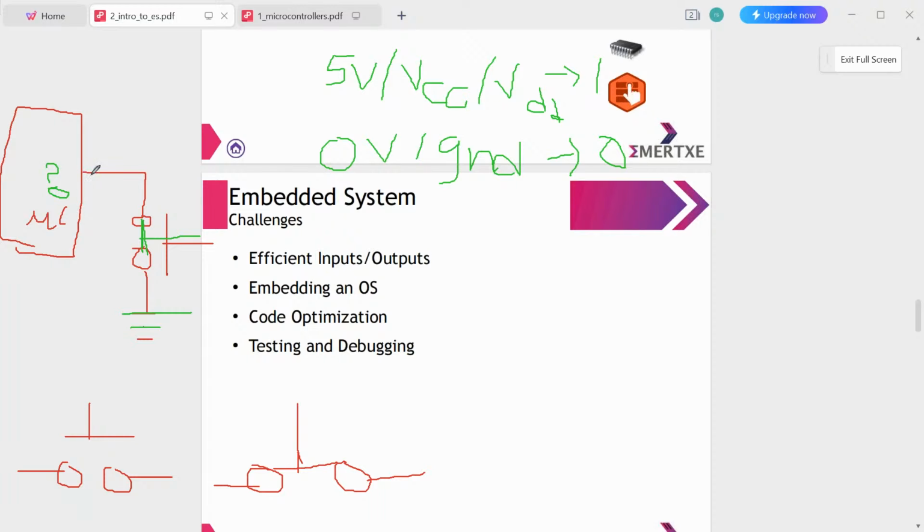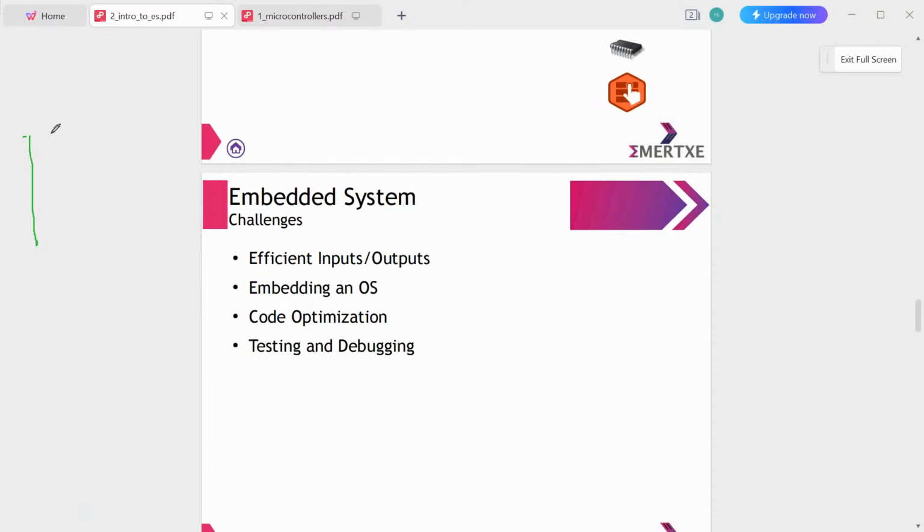At least, may I know where this pin is getting connected on switch press? Don't you think it is connected towards the ground, right? So here you will be getting the signal 0 when the switch is pressed. But what about the switch open? If I open the switch, what will be the signal at this pin?